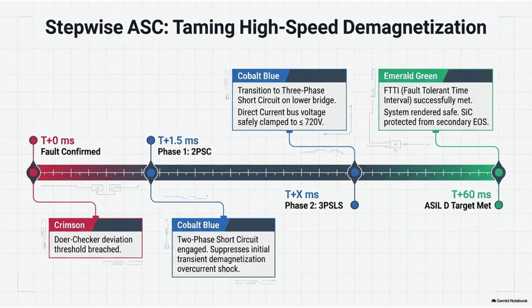Right. This involves a hardware-level error correction code, or ECC, running alongside a background cyclic redundancy check, a BGCRC. The architecture doesn't just store the data bits, it calculates and stores extra parity bits using Hamming codes. Hamming codes are just brilliant. They really are. They arrange the parity bits so they cover overlapping subsets of the actual data bits. If a cosmic ray flips a single bit, the hardware calculates the parity again, and the specific combination of parity errors will mathematically point to the exact intersecting location of the corrupted bit. And then the ECC hardware can silently flip it back. Autocorrecting it in less than 1 millisecond. Without the main software ever even knowing a cosmic ray struck the car, it acts as an invisible background checksum.